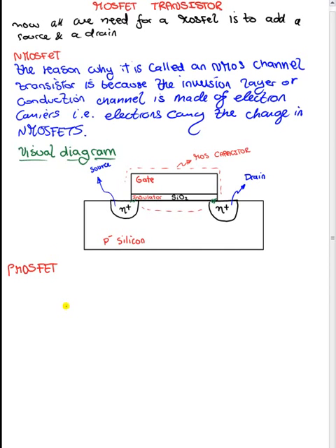So let's write that down. The mechanism for working these two devices is very similar. It's just opposite. That's why when you're working with equations, they tell you that all you need to do is just apply the same equations that you would with an N MOSFET for the PMOS. Just change, instead of VGS, change VSG, right? And that will do it.